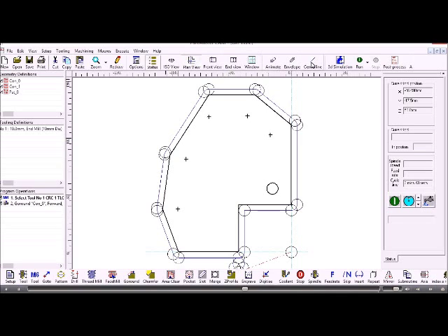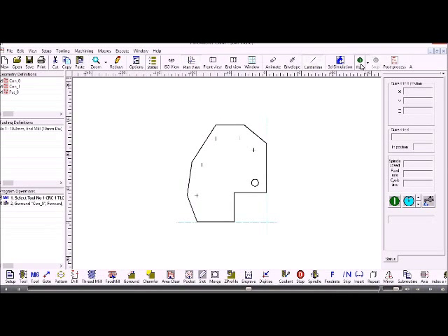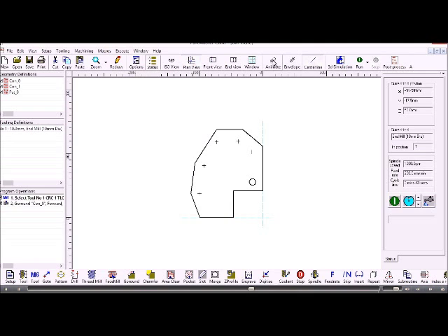So if I want to see just the tool center line, and then I run the job, so that's just showing me that. If I click into the graphics area, I can use the mouse to zoom in and out, so we can now see the arc approach movement onto that and the arc runoff. If we want to view the tool, we animate the tool and run the job.